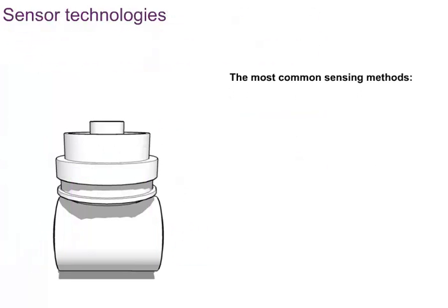The most common sensing methods used today are piezoresistive, capacitive, inductive, and silicon resonant. Before entering into the description of the various types of sensors, it's worth mentioning that over the years, the discussion on the technical superiority of one technology over the others has reduced its importance. The reason is that with present modern manufacturing and compensation technologies, the differences, although existing, are negligible from an application viewpoint. The only exception is the variable reluctance type, which is no longer used by main vendors.